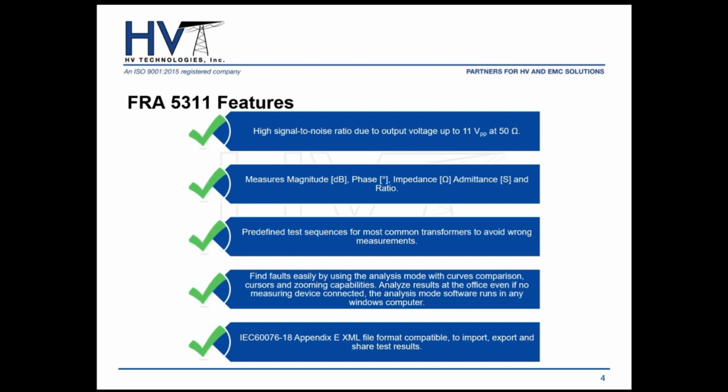With the analysis tool in the software, you can easily find faults, compare curves, and analyze the results. You can go into the field, do your measurements, and then take the curves that were produced to your office. You don't necessarily have to be connected to the device to analyze the curves. And one final feature that I think is pretty cool is that it complies with the IEC 60076-18 Appendix E XML file format.